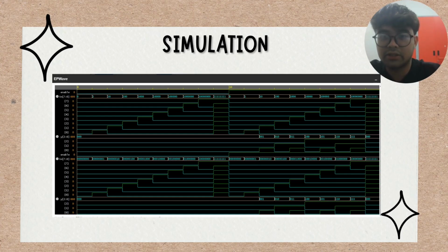Second, bitwise signal behavior. Individual input bits in[0] to in[7] toggle sequentially, and each transition is clean without overlap. This demonstrates proper stimulus generation in the test bench and ensures encoder outputs are not affected by multiple active inputs.